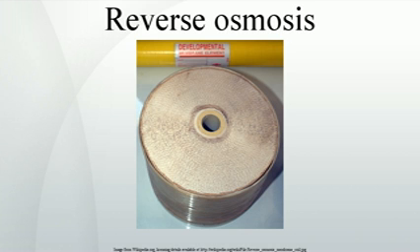New developments. Pre-filtration of high-fouling waters with another, larger pore membrane with less hydraulic energy requirement, has been evaluated and sometimes used, since the 1970s. However, this means the water passes through two membranes and is often repressurized, requiring more energy inputs in the system, increasing the cost.